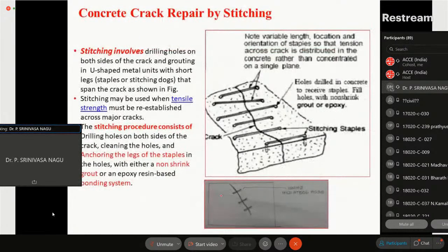And then the stitching repair you can see, because there are two parts separated. Bring them together. You have to design how to bring them together. You have to see how much force may be required to resist against the further expansion of the crack. Then you see this is also available in that code SP25 I told you, same figure.